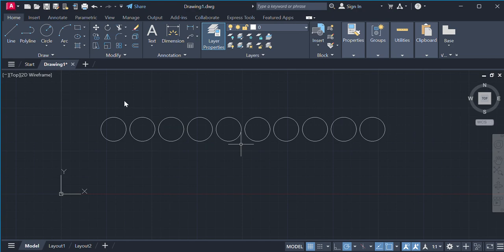So the reason you've now specified these layers is that you want to draw certain items using these layers. Currently, as is, the one with the tick is the layer that you're currently working on. If you want to make any other layer current, then you double click on that layer and it makes it current. Whatever command you carry out after that will have this new layer applied to it.